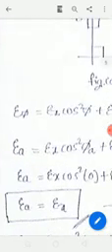Now let us determine, how can we determine? Using this equation, the general equation: epsilon phi equals epsilon x cos square phi plus epsilon y sin square phi plus gamma xy sin phi cos phi. This is the general equation you have to remember for the remaining analytical solution methods, right?